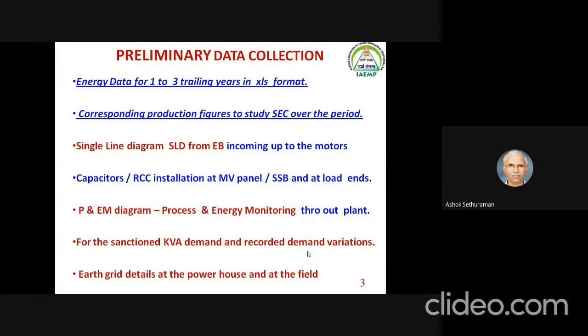This is more important. We can make the industry ENMS. Totally, we can make the industry energy management and associated monitoring and control achievable only if the energy meters are in place, and the in-situ energy meters are there in each and every machine and motor in the production and utilities. What is the sanctioned demand and what are the recorded variations happening with respect to the sanctioned demand?